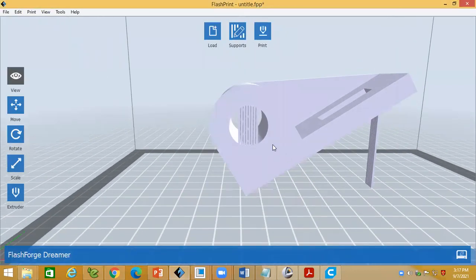After generating the support structures, you go for printing. Without supports we can't do it. In design for additive manufacturing, it says you have to choose a different orientation to reduce the support structures, as well as increase the strength and improve the surface quality of the 3D printed component. That is considered during design for additive manufacturing. You have to take care of all these parameters when you are placing this STL file on the build platform.